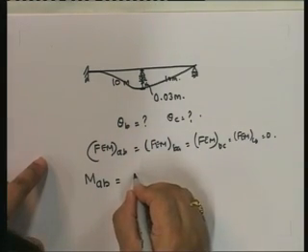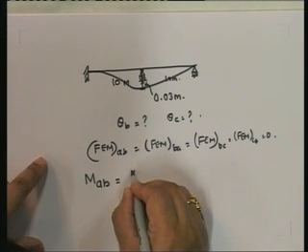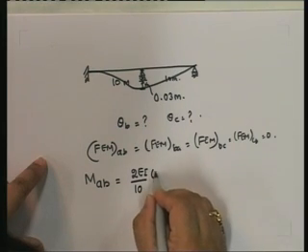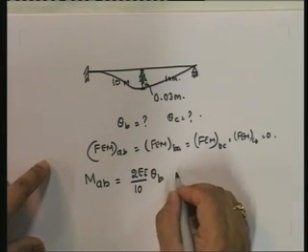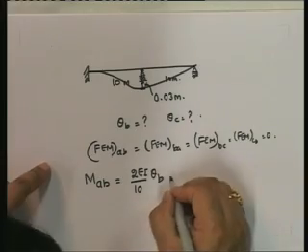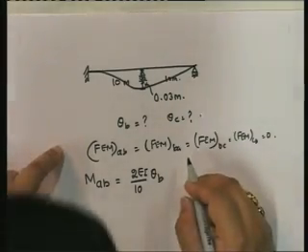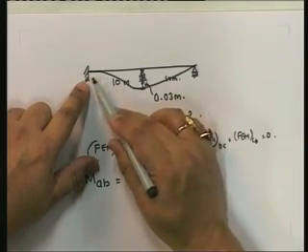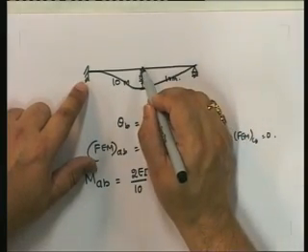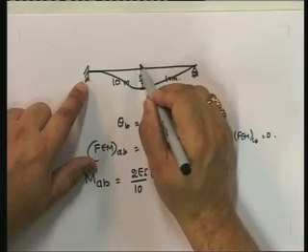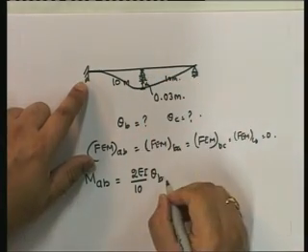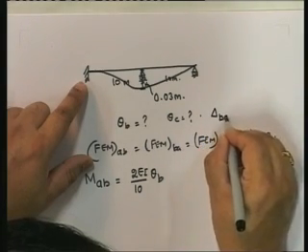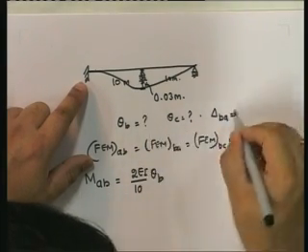substitute these values in, and we have the same compatibility conditions. So this becomes 2EI/L times theta B. Now, do we have a delta BA? Note that we do have a delta BA. This has gone down relative to this. I had always said delta BA is positive going up. So when it's going down, what is it? It's negative. So here you have delta BA as negative